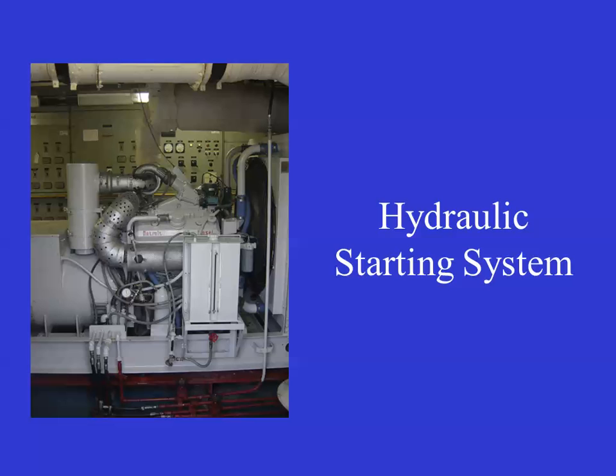The air compressor would be a hand start little diesel compressor, and then you could switch from electric to pneumatic, start up this little hand crank compressor, fill your start air receiver, and then start the motor that way. But that is the problem with electric: if you drain the batteries, how are you going to start the emergency diesel generator if you're dead ship and don't have power?